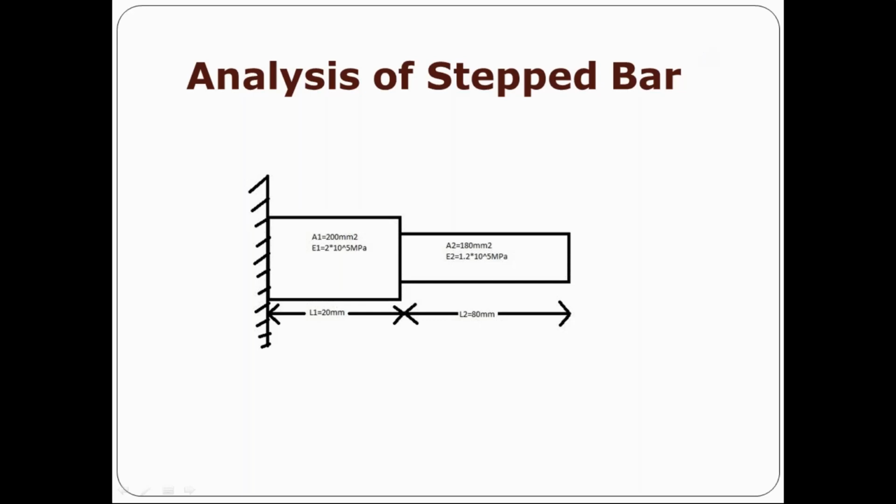Now, if you have the software, you can also do the necessary steps with me. The first thing is very important in ANSYS. I would like to solve this example in ANSYS. There is no need to draw the figure as it is. You can draw it as a line diagram. You have to always simplify the geometry in ANSYS. You can draw these two step bars as a line diagram.